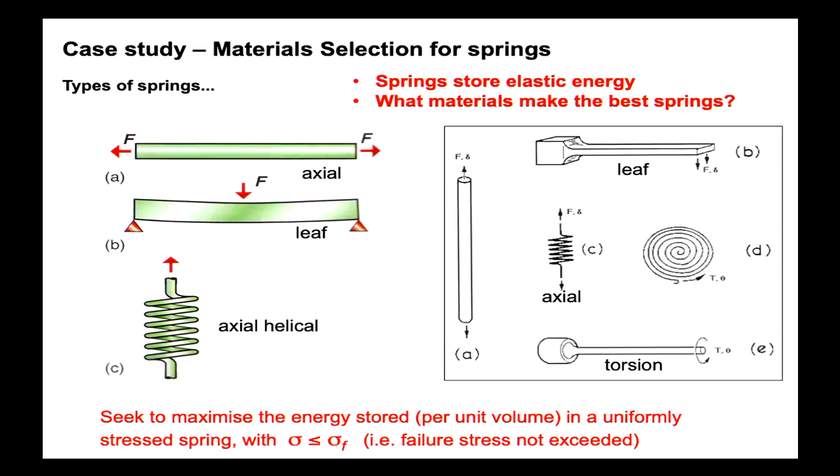But some case studies, which I think are a lot more fun, a lot more interesting. Springs. Springs store elastic energy. They release that elastic energy in a certain delta T, or, there's a certain time in which the spring can release that energy. And some texts talk about spring rate. Now, that's not the delta T. That's another word for spring constant, K, force divided by associated deflection.